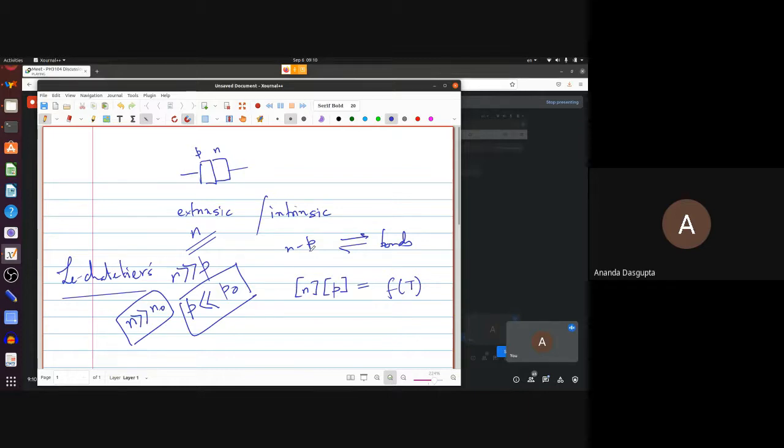It might not, because remember, even though the mean in the sample actually burned out at 4 amperes, there are lots of fluctuations in your procedure. And unless you are paying a huge amount for very highly precise production levels, your given diode might very well burn up even at less than 1 ampere. So you don't even want to try to go close to that. Okay? So the real process usually is the breakdown of the junction, which destroys the diode for all practical purposes. Whether it burns up literally or not, that depends. That may not happen.